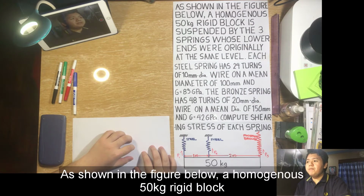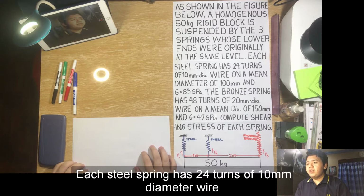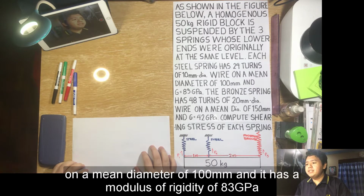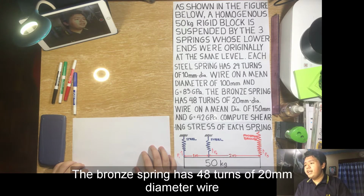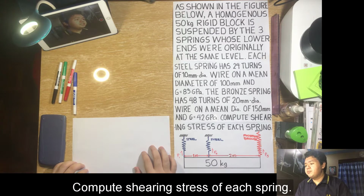As shown in the figure below, a homogeneous 50 kg rigid block is suspended by the 3 springs whose lower ends were originally at the same level. Each steel spring has 24 turns of 10 mm diameter wire on a mean diameter of 100 mm, and it has a modulus of rigidity of 83 gigapascals. The bronze spring has 48 turns of 20 mm diameter wire on a mean diameter of 150 mm and a modulus of rigidity of 42 gigapascals. Compute the shearing stress of each spring.